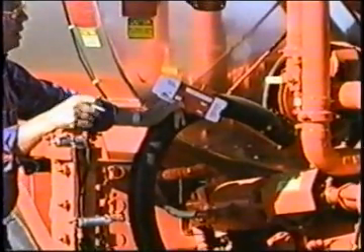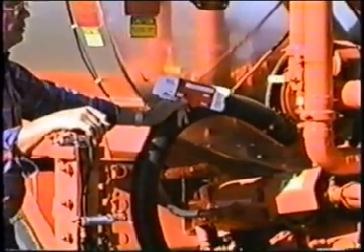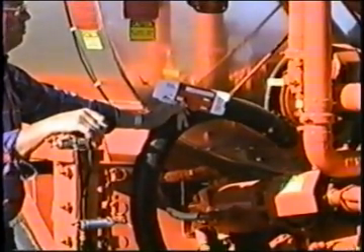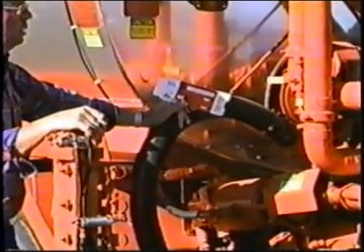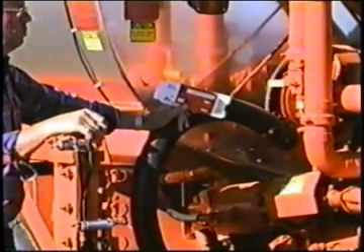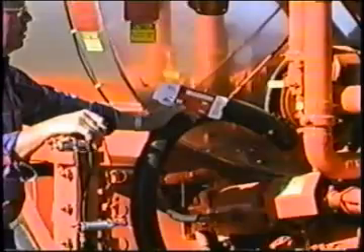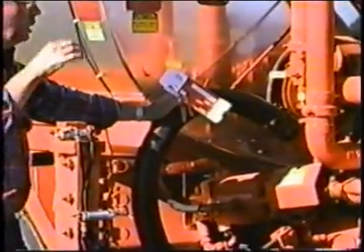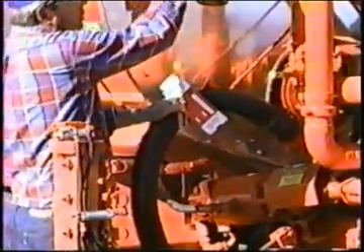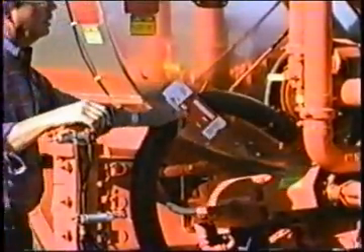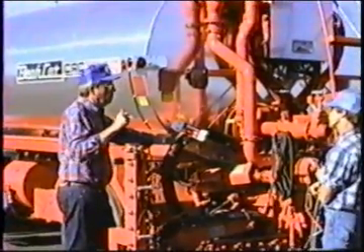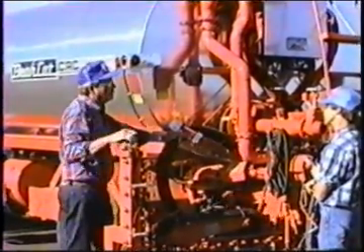Okay, now if we back the bypass valve down to the 8 pounds, then that's the maximum pressure that the relief valve can create. And as we narrow the spray bar down, the bypass valve would let the excess flow go back into the tank, because we have set it at 8 pounds, and when it tries to make more pressure, the excess fluid goes back into the tank.